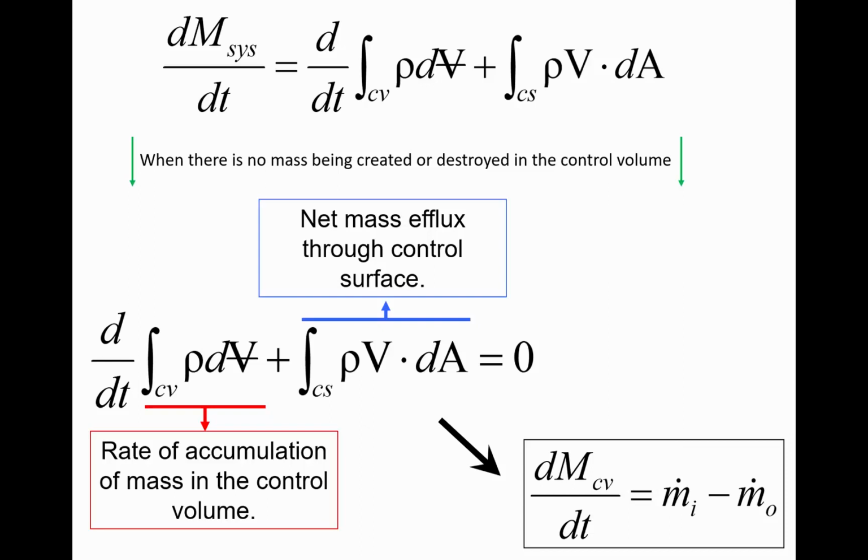And that's kind of what we did when we were looking at that reservoir example at the end of Tuesday's class, the Oahe reservoir, where we had flow going in, flow going out, and we were essentially finding out how long until the reservoir was emptied down to zero stored water, and we solved for the time. So that's just one illustration of the types of problems that we can solve with this Reynolds transport theorem equation.